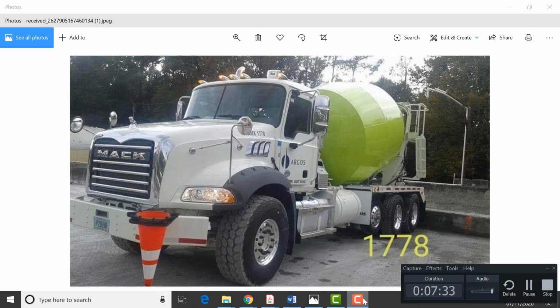The example design mix calls for 1,620 pounds of coarse aggregate and 267 pounds, 32.0 gallons, of water per cubic yard. The aggregate has an absorption of 2.50%, and the total moisture content is determined to be 6.53%. Calculate the adjustments to batch quantities per cubic yard. Figure the water adjustment in pounds and gallons.